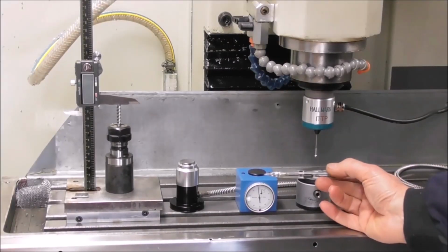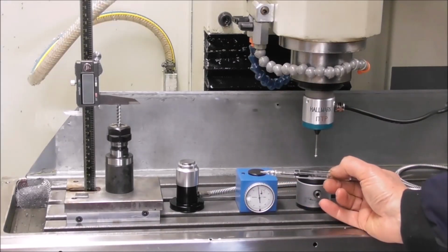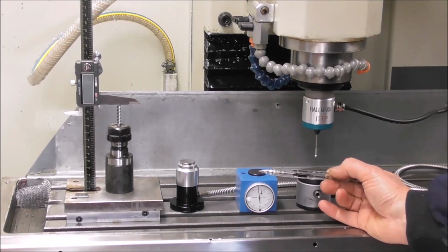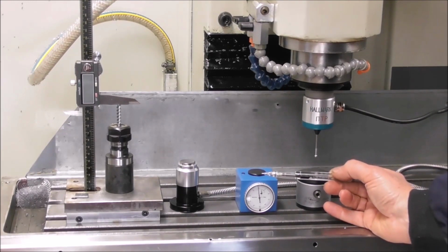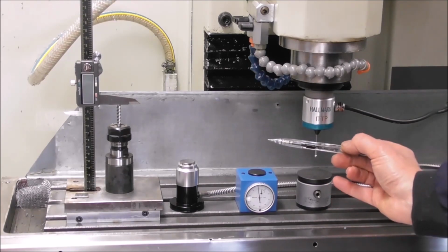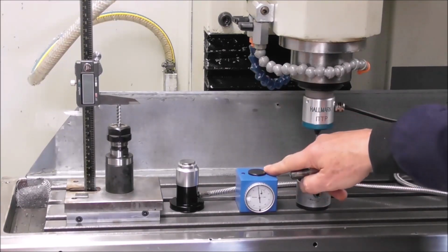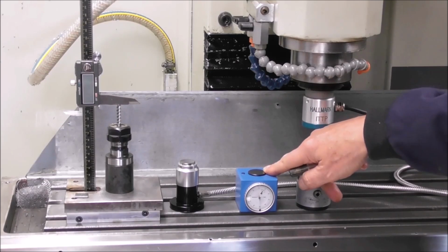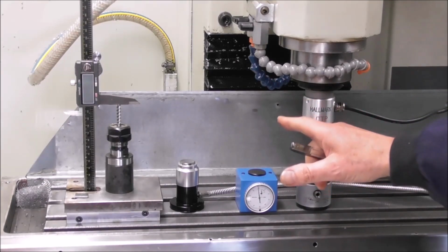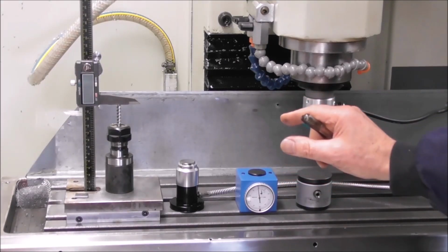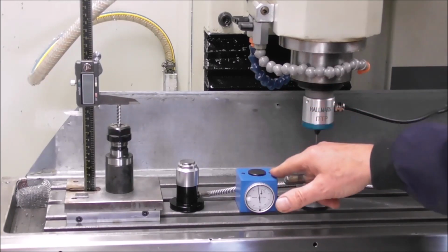Remember, most of you will only be using your tool setter to set your tool length offsets, the length of your tools. And if you're only using it for your tool length offset and you're using a manual setter, you're just coming down to 0 on the dial, for example, and hitting one button on the software which loads the tool length into the tool tables. That's not a lot of work.